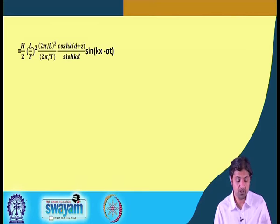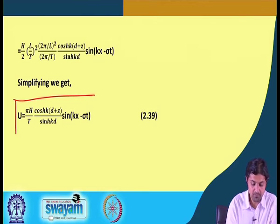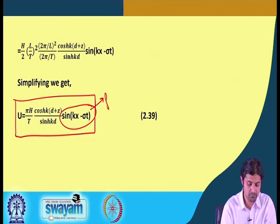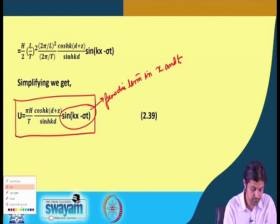So just doing manipulation, writing in terms of L and T, this equation you can remember but not mandatory, since you will definitely remember the velocity potential equation, and therefore you can derive this u even for your assignments and exams. So it's pi H by T cosh k(d plus z) divided by sinh kd into sin(kx minus sigma t). This is the periodic term in x and t, sin(kx minus sigma t).